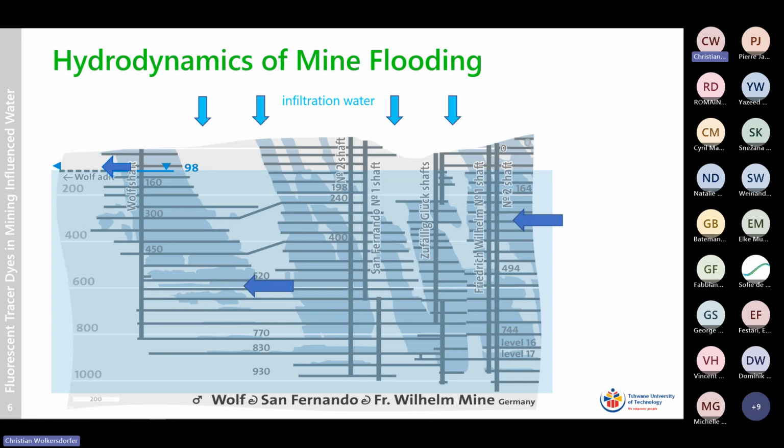And obviously it doesn't have to be only one point of discharge. It can also be several points of discharges. This really depends on the setup of the mine. So there is a general flow direction inside the mine, but in mines, there can also be flow, and you see this down here, between shafts, a convection cell where water is flowing up and then it's flowing horizontally and then it's flowing down. There are convection cells, but the water can even flow within a shaft, up and down.